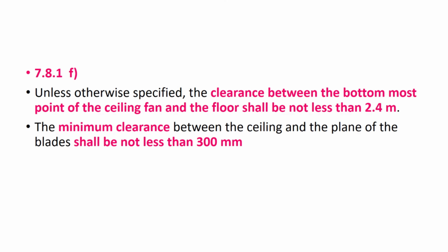Now what I am trying to tell here is that in case it is an unreinforced foundation, the angular spread of the load from the base of the column or the wall or the bed plate to the outer edge of the ground bearing is not more than 1 vertical to 0.5 horizontal for masonries and 1 vertical to 1 horizontal for cement concrete. Now I am trying to tell you how the loading pattern will go below.